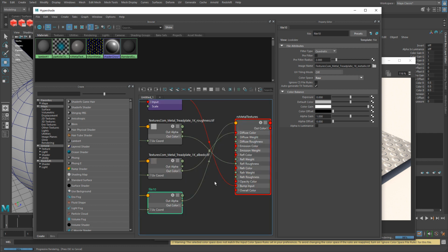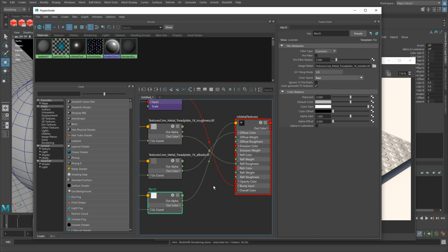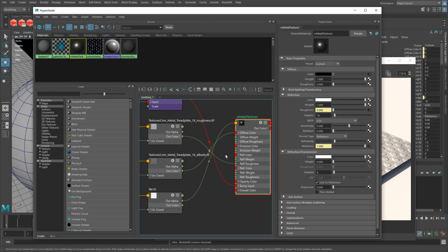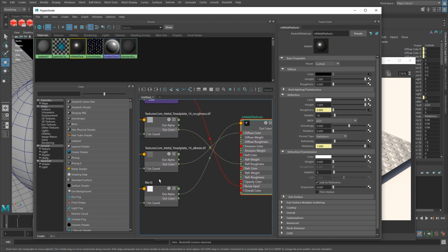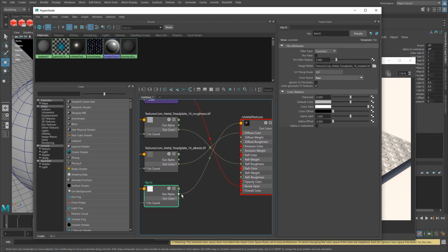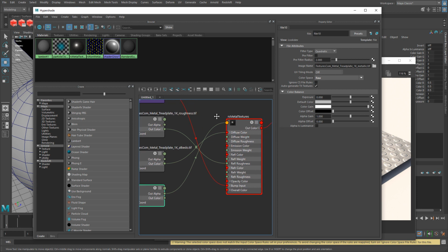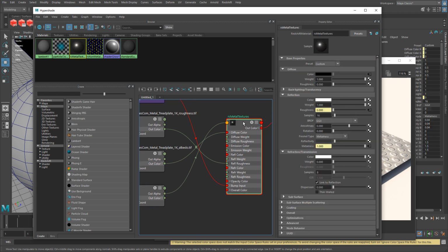Now in the current version of Maya that I'm using, which is 2020, what I'm seeing in the main node is a kind of visual bug that shows my metallic texture out alpha is being connected up to somewhere that you can't really tell what it is. So this is just a display visual issue. If you select the main node and hit 1, 2, 3, or 4, this will cycle you through different options for that material and how many inputs you get to see.